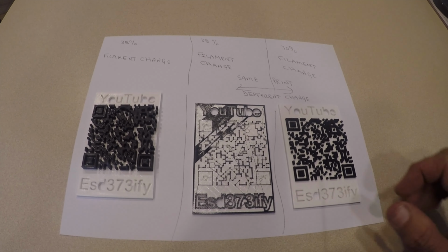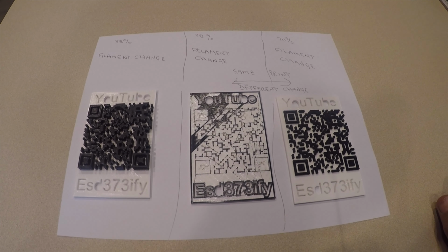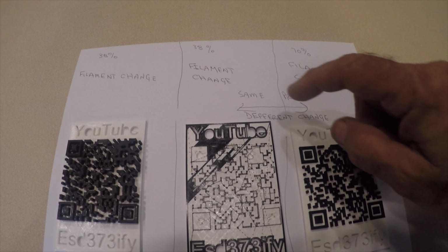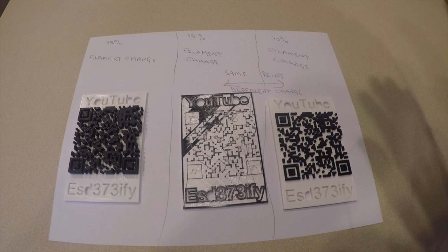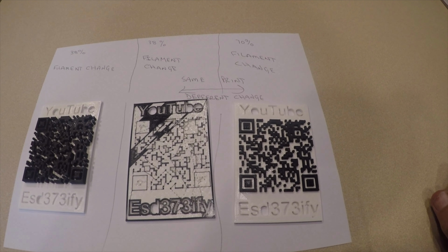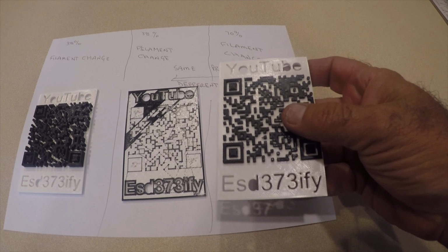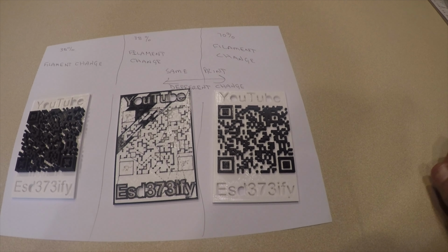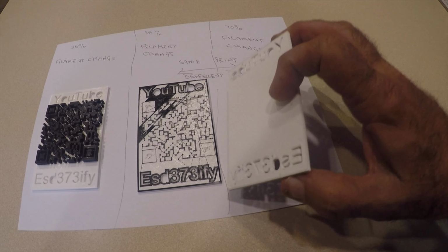So then what I decided to do was I decided to make the thickness, the total thickness, around 5 millimeter, and I didn't take into consideration that the whole percentage thing changed. So at 38%, the same as this one, I did a filament change, and this is what happened. So next, I kept it at 5% total, and this time I watched it, and when it got to 70%, I did a filament change. It's a lot better. Unfortunately, my Android will only read this periodically. The iPhone will read it every time. So the next print I'm going to do, it's going to be a total of 3 millimeter.